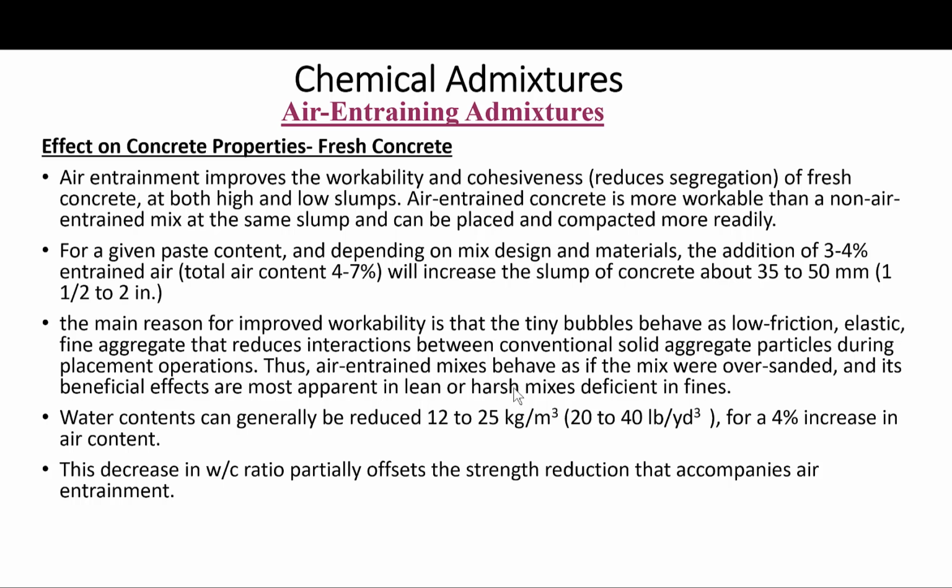But the main reason for improved workability is that the tiny bubbles behave as low friction elastic fine aggregates that reduce interaction between conventional solid aggregate particles during the placement operation. So air-entrained mixes behave as if the mix were over-sanded. That's exactly what it does. And its beneficial effects are most apparent in the lean or harsh mixes deficient in fines.